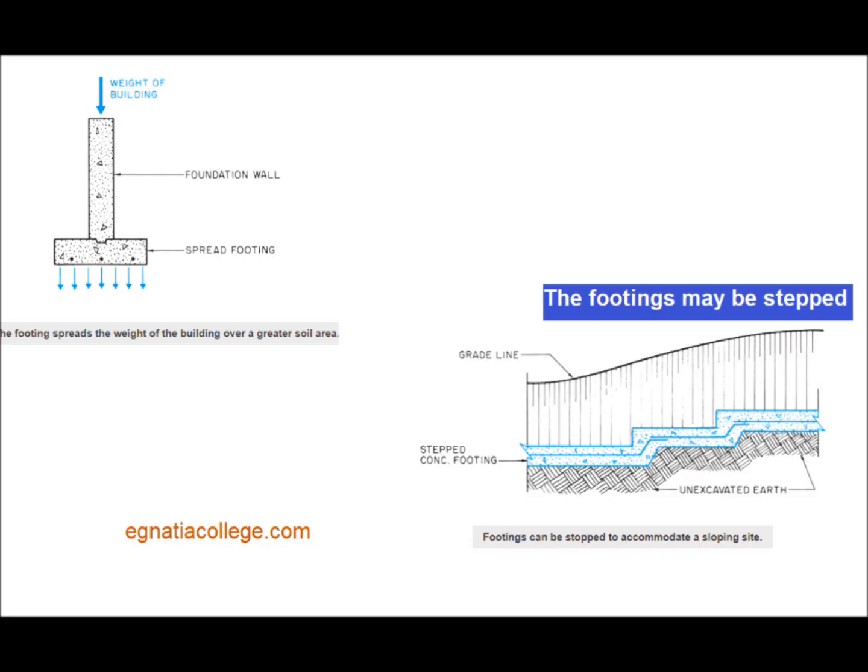These footings are placed on unexcavated earth to reduce the chance of the soil compacting under them. This means that the excavation contractor must measure the depth of the excavation accurately. The footings may be stepped to accommodate a sloping site. This requires measuring the depth at each step of the footing. Information about the footing design is found on the foundation plan and building elevations.